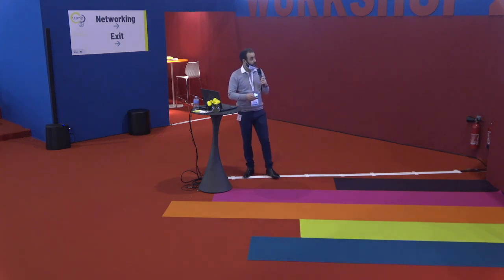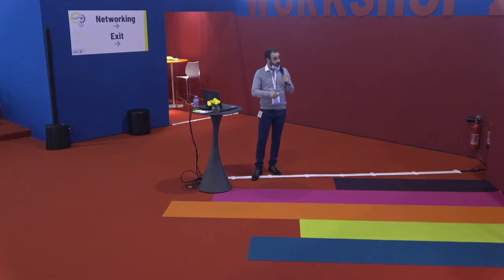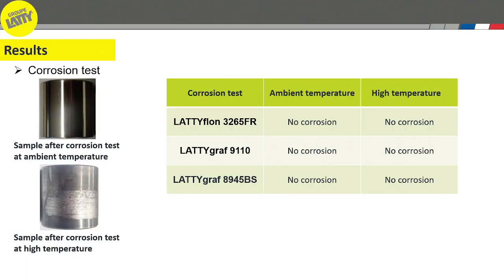Okay, here we have the result of the corrosion test. For both corrosion tests, at ambient temperature and high temperature, no corrosion occurrence was observed, and this is probably due to the corrosion inhibitor that we used during the manufacturing, which protects the stem from corrosion attacks, and more especially galvanic corrosion.